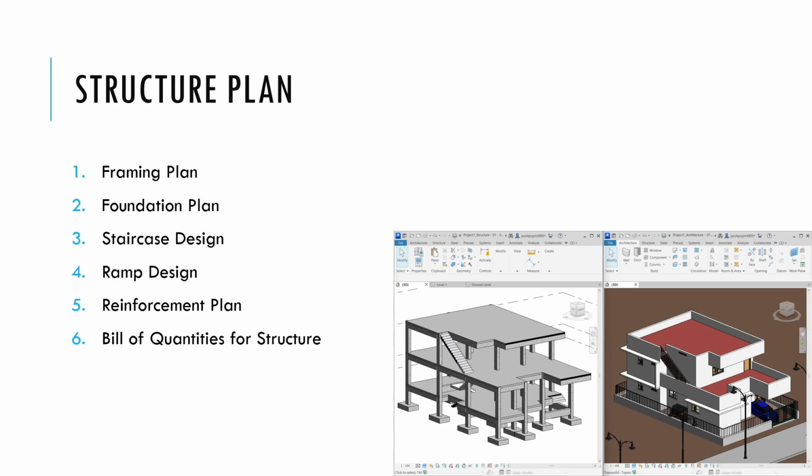Okay, so previously everything was done in AutoCAD, everything is 2D, and now we are doing the same in Revit, but the work procedure is totally different. So here we make the 3D model first and coordinate with architecture. Once the design is ready, then we'll go for the drawing. Okay, so don't try to make a framing plan on the first day. Just do the model first. So once you have the framing plan, then you are aligned with the architecture.